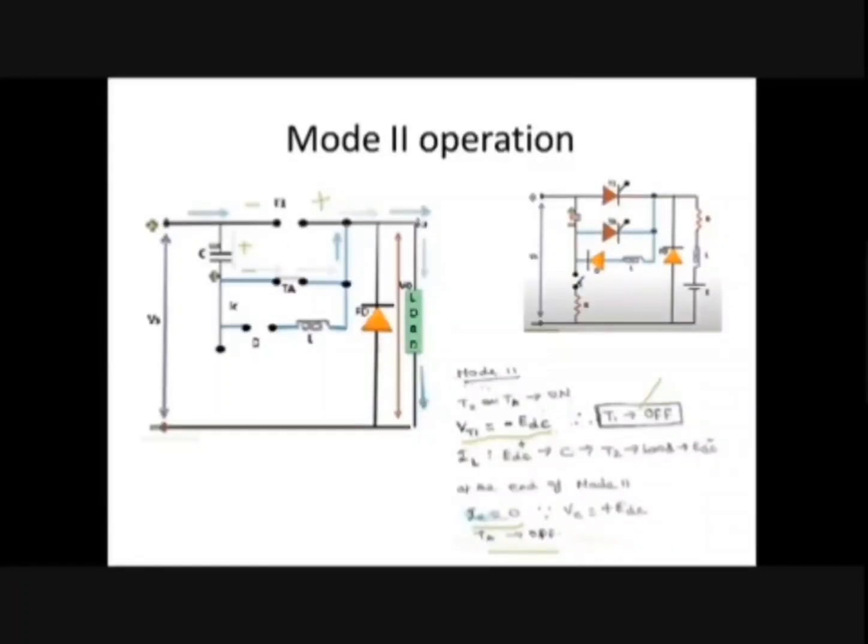The circuit will go to the initial stage. Now both the SCRs are in off state, so that the circuit will go to the initial stage. So we call this commutation as a voltage commutation or class D commutation or auxiliary commutation.